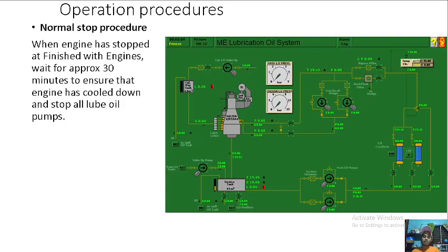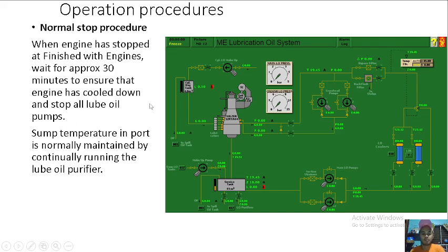So that's for starting. And for normal stop procedure, when engine has stopped, finished with engines, wait for approximately 30 minutes. In this engine, the manufacturer wants 30 minutes cool down to ensure that engine has cooled down before stopping the lube oil pumps. Some temperature in port is normally maintained by continually running the lube oil purifier.